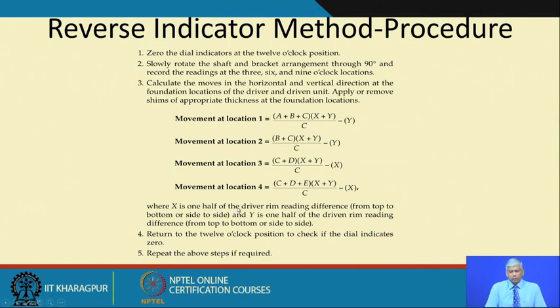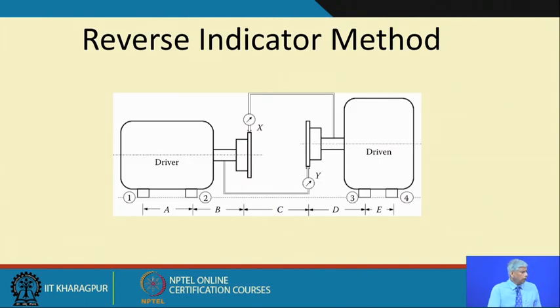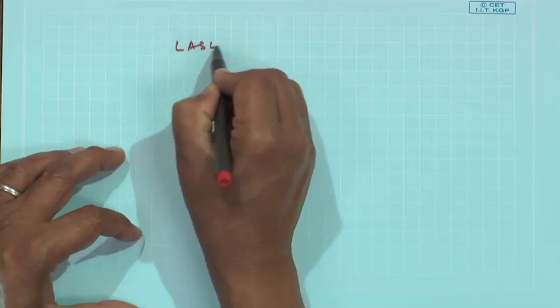So, this is a process people do to remove misalignment when they are installing machines, and this could be measured by dial gauge, but if these are large systems, they are rotated slowly by hand. Today, of course, we have laser based systems.